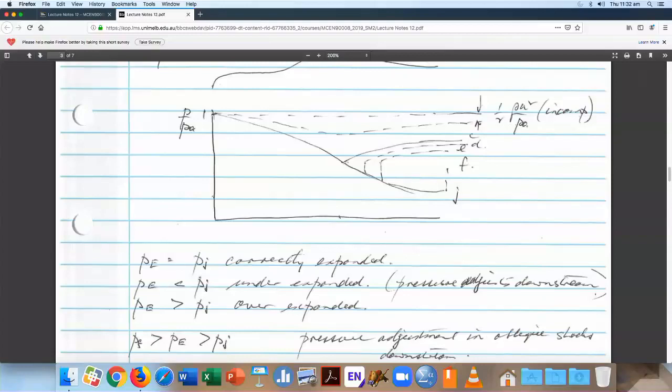And so I've drawn these lines here. So this is the pressure rising in this continuing expanding area because the flow is subsonic. And I can have E and D in here until I reach this boundary between M equal 1 at the throat and the fully subsonic case. The only place M can be equal to 1 is at the throat, the minimum area. Right, so that's the picture that emerges.